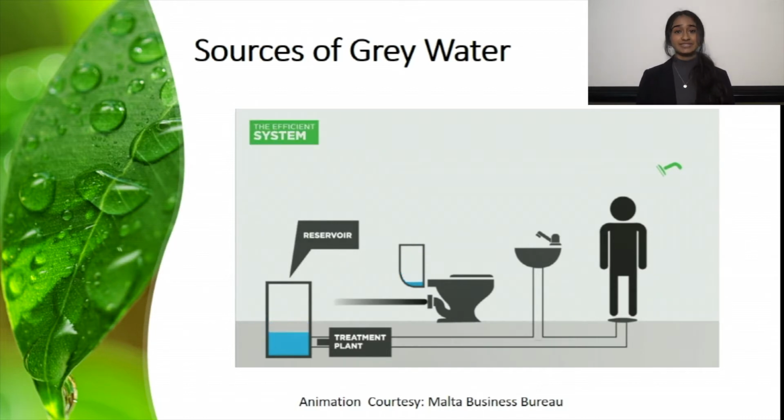A typical toilet tank is designed only for using a single source of water, fresh water. The reason for my suggestion to not use the freshwater inlet for gray water is due to the complications of cross-contamination, particularly when there's a need to switch between gray water and fresh water. Accordingly, if the toilet flushing system is designed with a dual water inlet, then the valuable fresh water can be easily isolated in the toilet whenever the gray water is available.